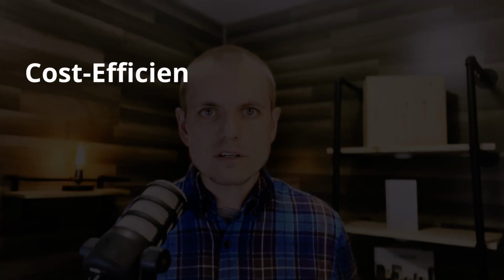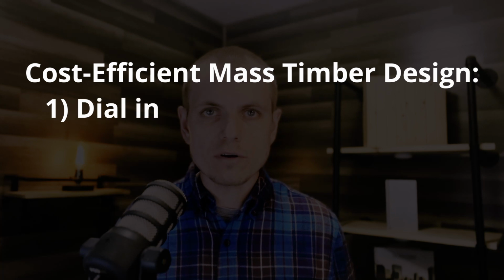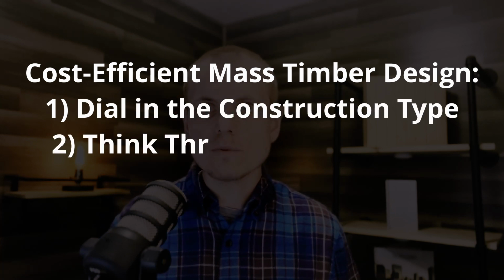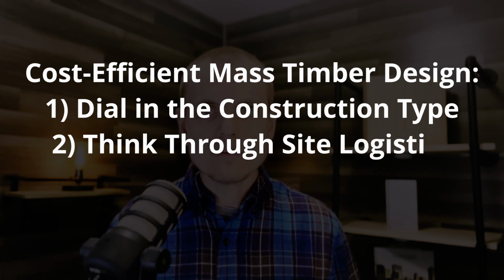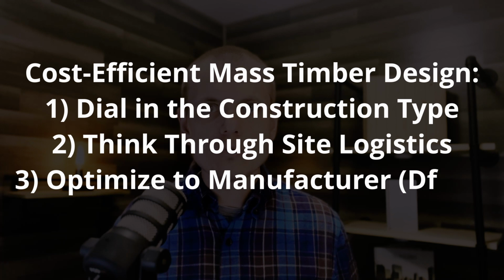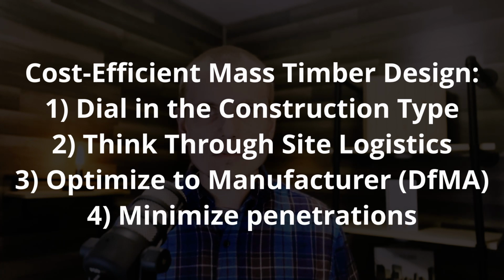Maybe my 4 takeaways I would give you at the end of this video is: number 1, fine tune the construction type to make sure it's really dialed in to the specific needs of your project. Number 2, think through the construction logistics. It's more than just what's happening on the drawings. You have to think through what's happening on the job site. Number 3 is understand and work within the capabilities of the manufacturer that is supplying the mass timber for your project. And number 4 is to minimize the penetrations through the timber members to the maximum extent that's possible.